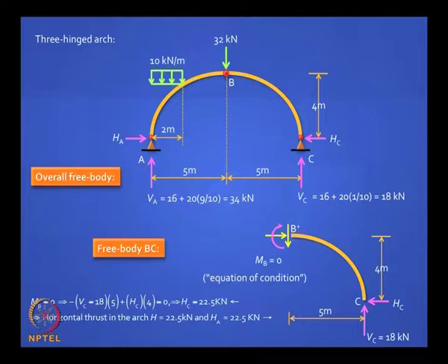Let us take a slightly more complicated problem. This is not simply supported. Here you have 2 hinged supports, which means you have the possibility of a horizontal reaction coming in. This would be normally statically indeterminate or over rigid, but for the fact that there is an internal hinge provided at the crown, and so what is this kind of arch called? It is called a 3 hinged arch. Okay, you give a hinge, and earlier they did this deliberately. Why did they do this deliberately?